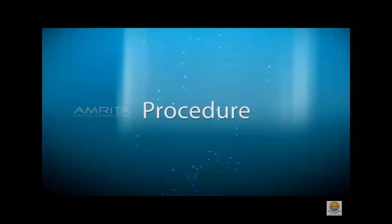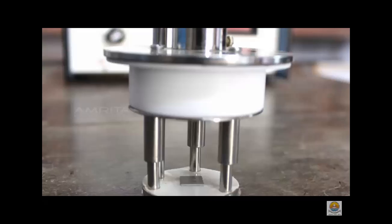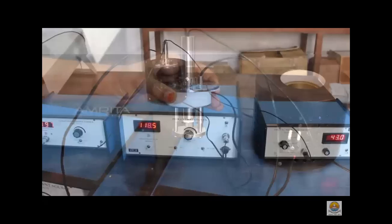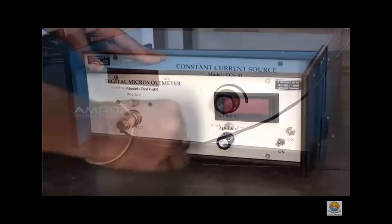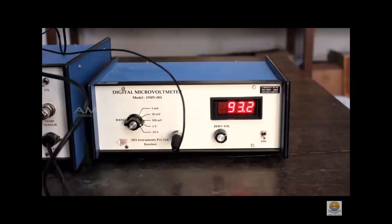Procedure. The sample is loaded. You can place any sample there. Mount the four probes on the thin slice of the sample without damaging it. A constant current is passed through the outer probes, connecting it to the current source. The voltage developed across the middle two probes is measured using a digital voltmeter.